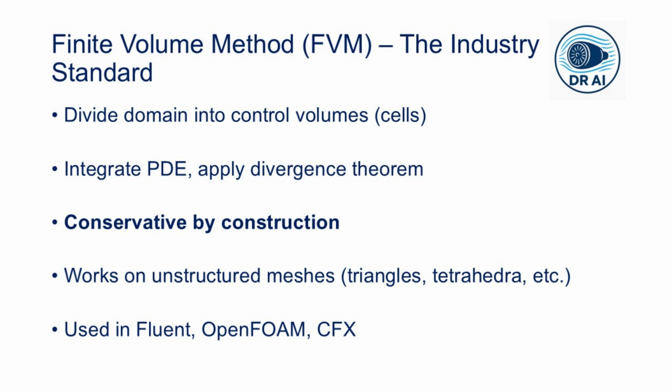Now moving on to the finite volume method, FVM, which is often considered the engineer's workhorse. This is the king of commercial CFD, including codes like Fluent, CFX, OpenFOAM, and Star CCM Plus, all of which use the FVM. Instead of points, FVM divides the domain into control volumes or cells. The governing equations are integrated over each cell. Then the divergence theorem, which is Gauss's law, converts the volume integrals of divergence into surface integrals of flux.